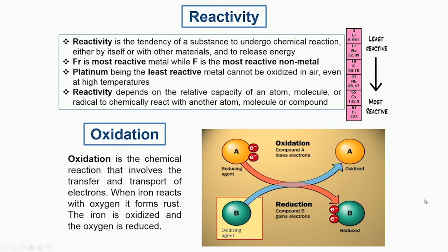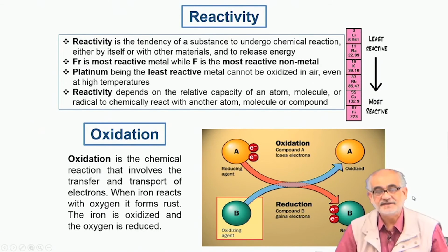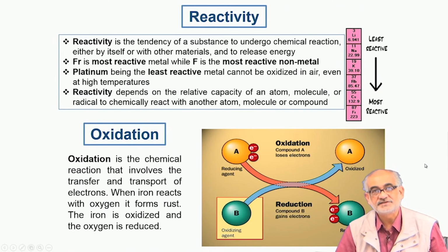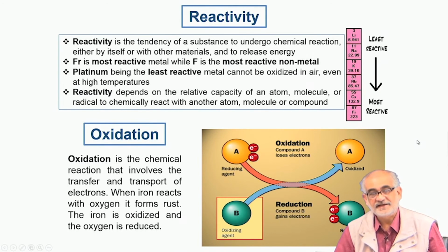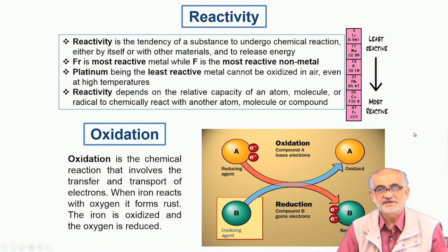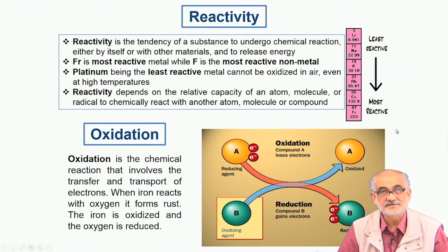This is how, in most cases, the undesirable phenomenon of oxidation takes place. And please remember that this oxidation is much more aggressive at high temperature, when the mass transport is faster and the growth rate of these oxides onto the surface of a metal or any other solid is much faster.